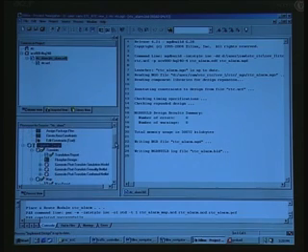See, this implement design, you remember I had given rerun and it has completed. Earlier when I gave rerun, there was a question mark implying that it was running. Now having completed, it gives a tick mark. For example, I want to see the translation report. What you do is just double click on the translation report. On the right you get the report here, and it simply says number of errors is 0, number of warnings is 0.